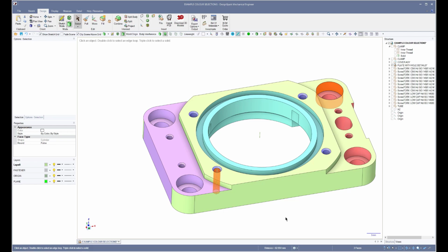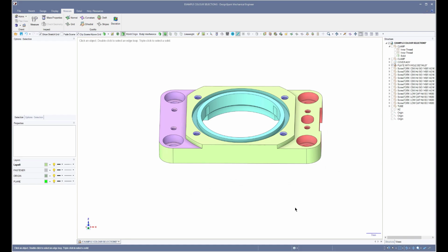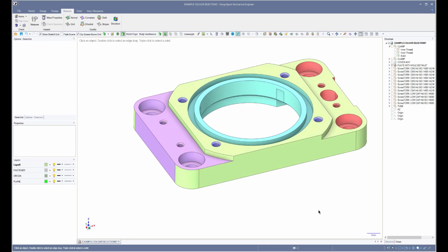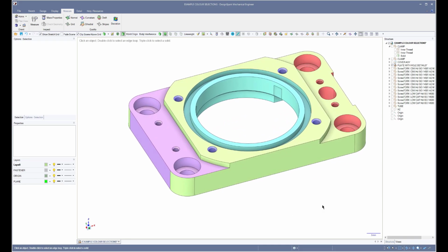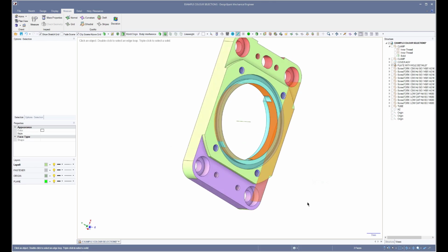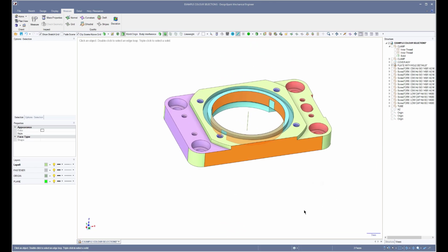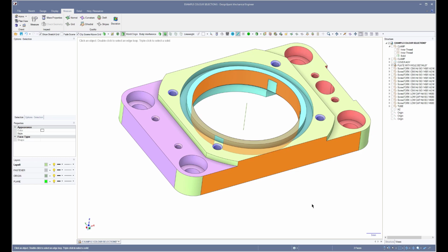Now, because this was done in standard select mode, any noted distance always means the objects are parallel. You have to note that in standard select mode, the features that you're measuring have to be the same. So I can measure this face, and let's just select the other face, and I get a parallel distance of 50.5. But if I select this curve face and this face, I don't get any sort of dimensional feedback between the two because they are dissimilar.